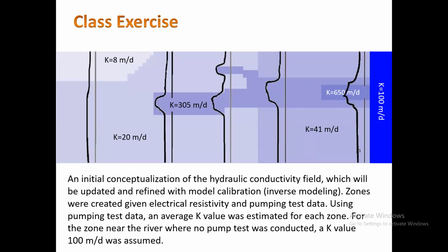Any water that flows on the top will flow either in this direction or in this direction, but no Q here. So if I told you that this is a no flow boundary, this means that Q here is equal to 0. No flow is occurring here, and also no flow is occurring at this boundary, and no flow is occurring at this boundary because this is the groundwater flow direction. So all these are no flow boundaries.